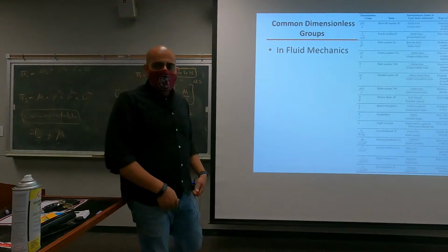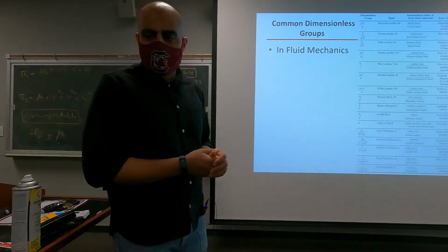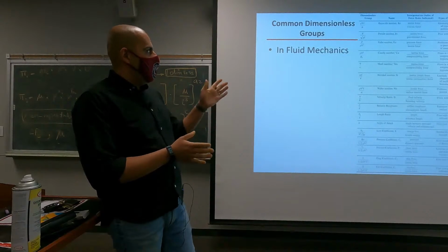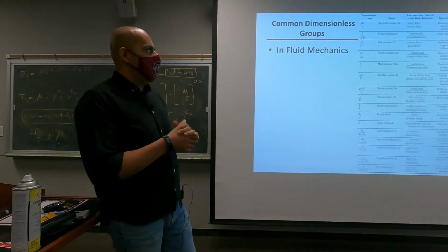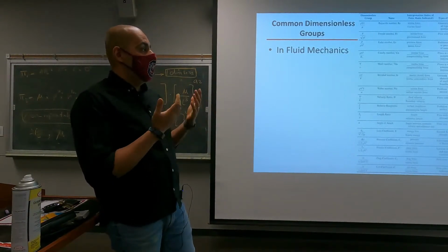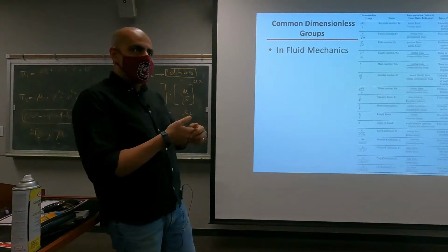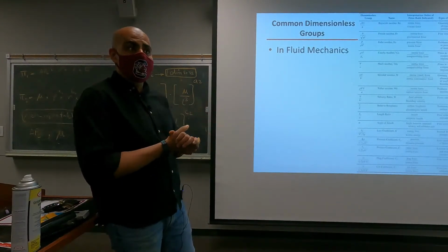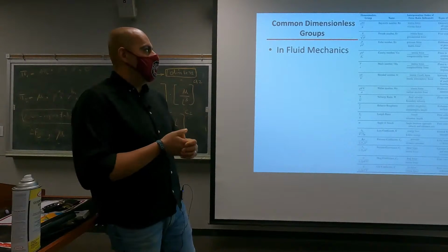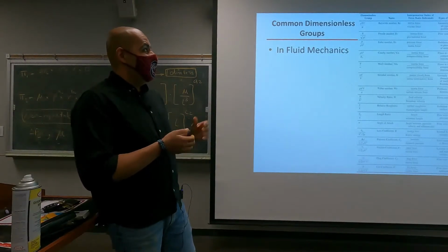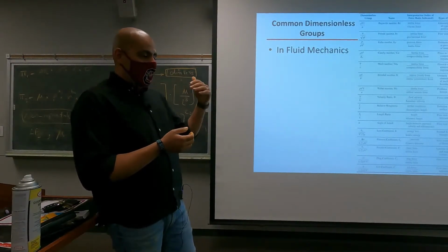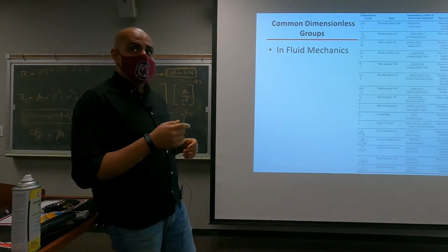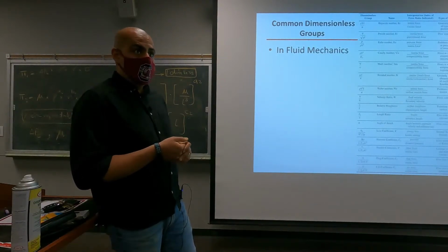We have the onset of turbulence or onset of laminar flows, which can be distinguished based on Reynolds number. For example, for flow over a flat plate, which is very common in aerodynamics, you have flow over wings, right? We can assume that those are flow over a flat plate. Your flow starts to become turbulent when your Reynolds number reaches 5 times 10 to the power 5.